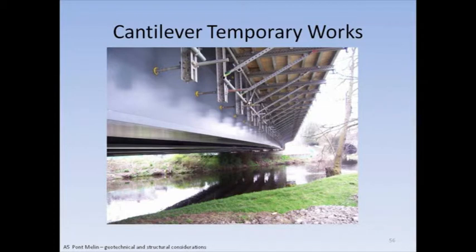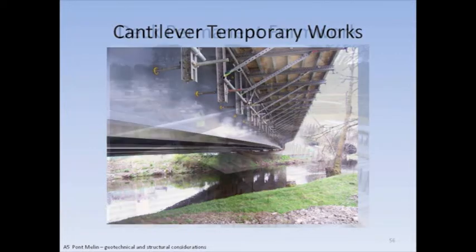The cantilever for the bridge, as well as having the twist in it and the skew in it, has a curve of the highway in plan as well, although the beams are straight. And to achieve that, originally we looked at having a precast cantilever unit to be able to progress the works quickly. But because of them being cast with straight lines and the size of the bridge, the concern for a threepenny bit effect was such that we went back to having a cast in situ edge to the bridge.